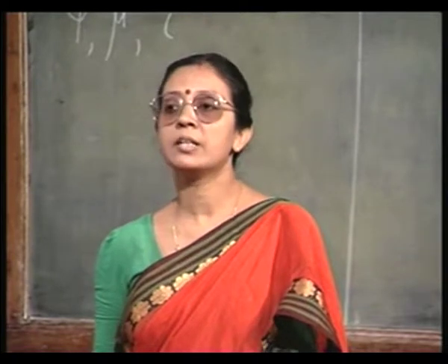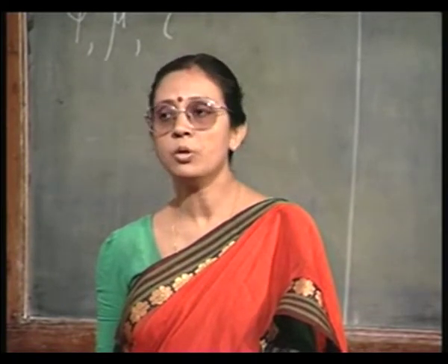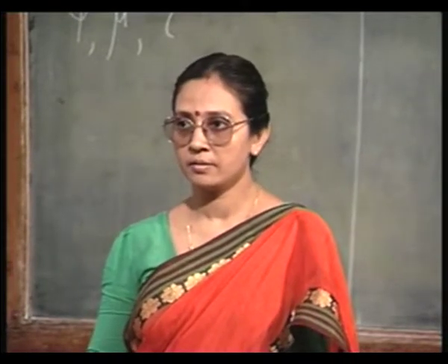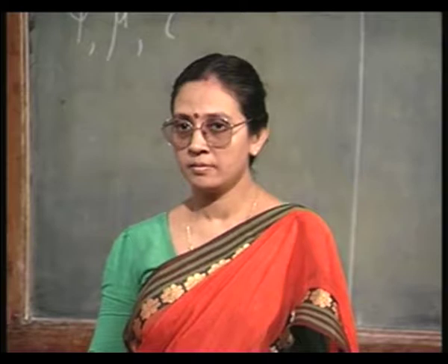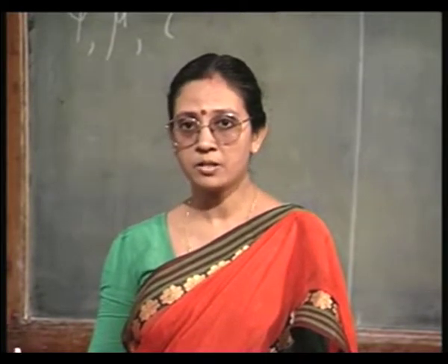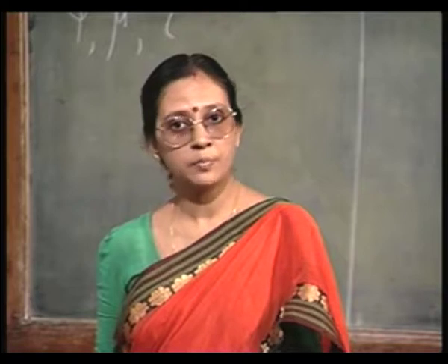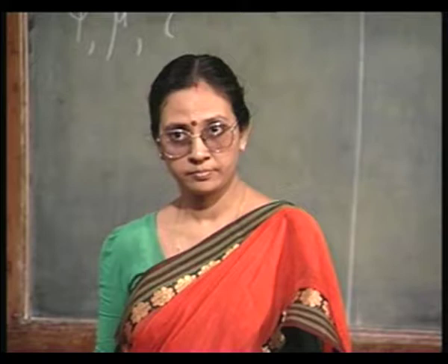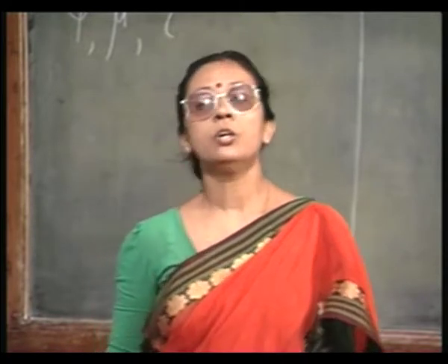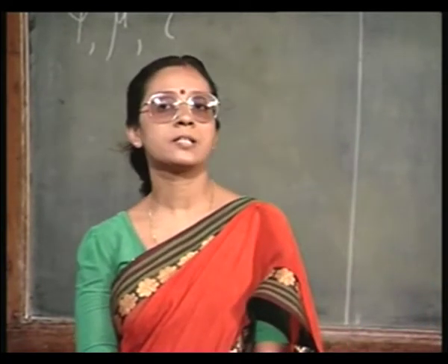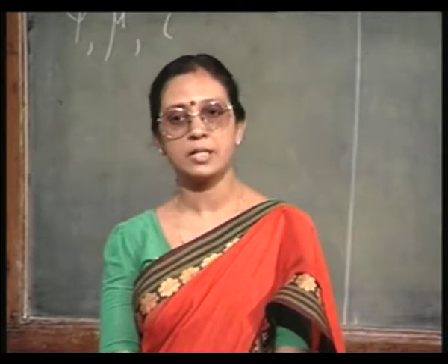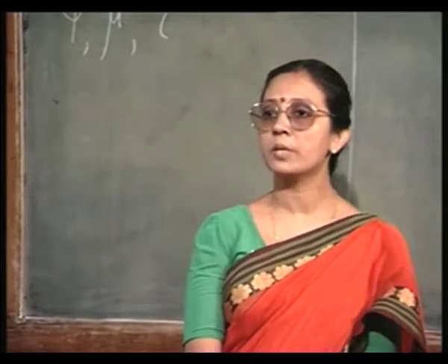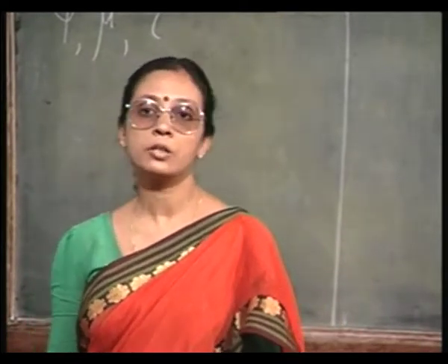because even if in the damaged region the lifetime is low, it does not matter, because the depletion region is on the other side. The device activity will be taking part on the other side of the peak concentration, not towards the surface. So, this in a way helps us a little bit because the damaged region is lying closer to the surface. We can relax some of the requirements; we may not have to go for the total recovery of lifetime.